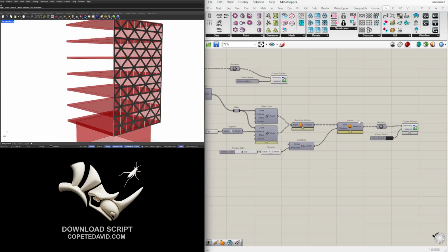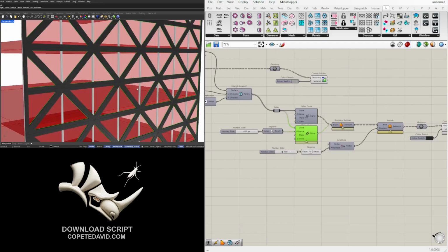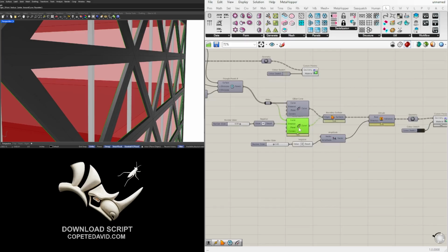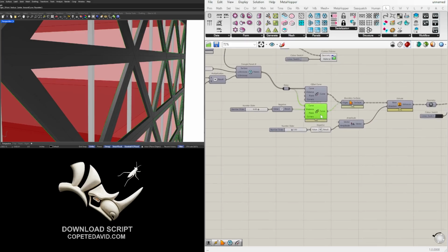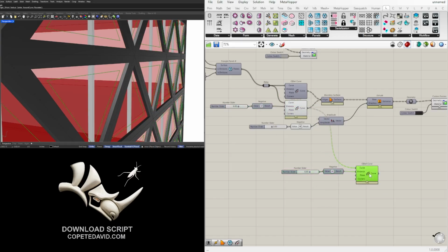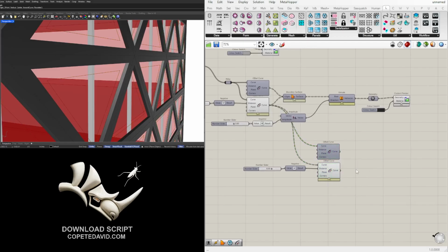For this next part, we are going to be creating the dynamic portion of the facade. So we need to go back to the offset. So this one, because that creates the panels on the inside. And what we'll do is use that and offset it again, because we'll be using a curve attractor for this one. So we'll offset it again using an offset component. And I like to offset it by 0, like we did with this one. And now with that, we'll be creating a loft.